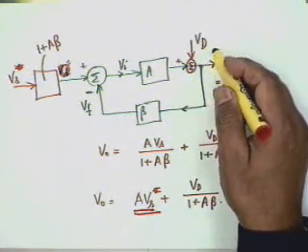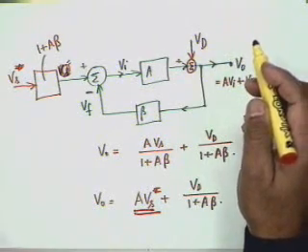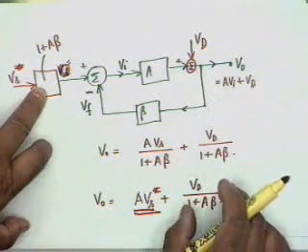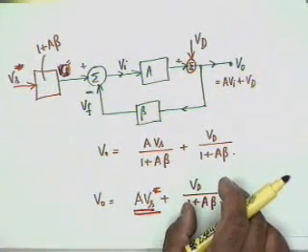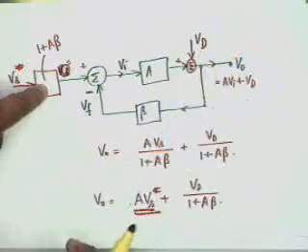But now, Ankur, this is for your attention. Now there is a problem. You cannot make up for the gain by a pre-amplifier. Why not? Because the pre-amplifier will have noise. Noise is omnipresent. It does not depend on the signal level. The noise generated by an amplifier, a device, a resistance, a capacitance, or whatever the device is, is independent of the signal, and therefore the noise generated by the pre-amplifier shall also be amplified.